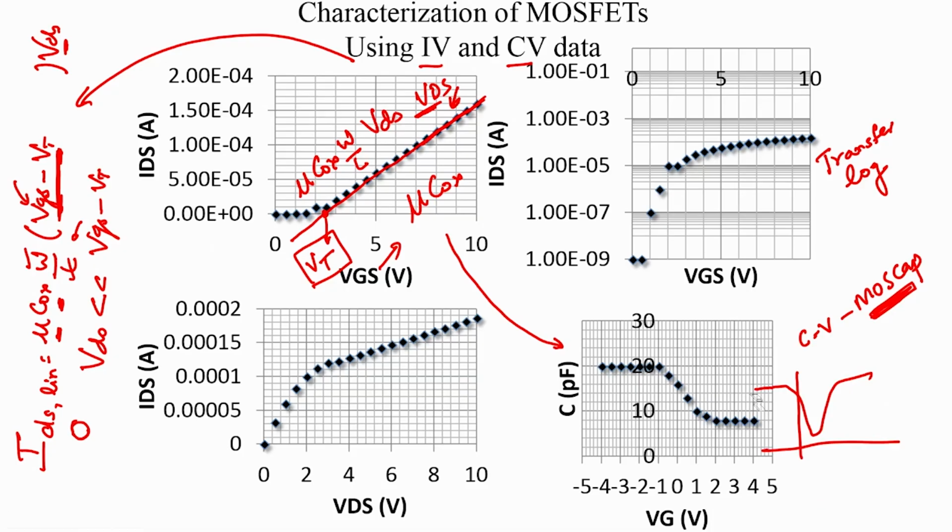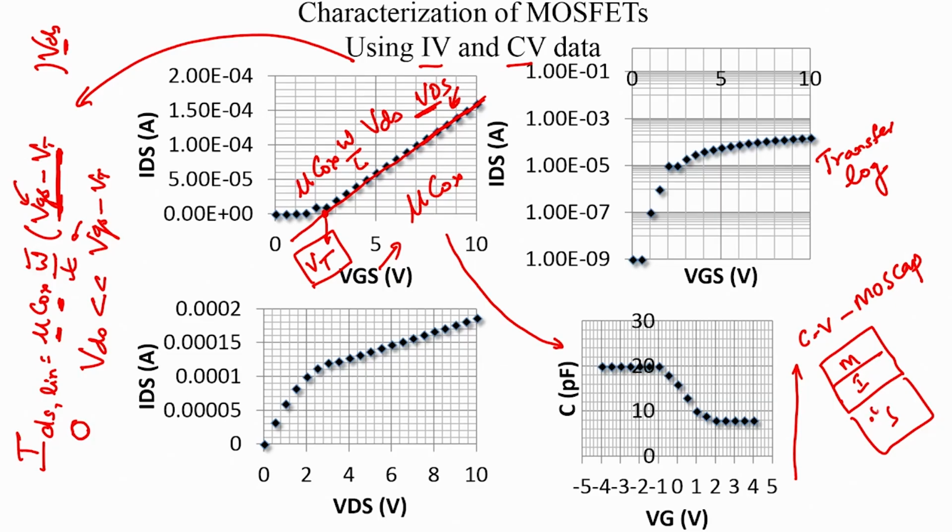And why is that? It is because the high frequency characteristics flattens out in this region simply because the thermally generated electrons in the bulk are not able to respond to the change in the applied signal. The generation rate of electrons is not fast enough. And a MOS capacitor has to rely only on the thermal generation rate, because all the electrons are coming in only from this generation mechanism.